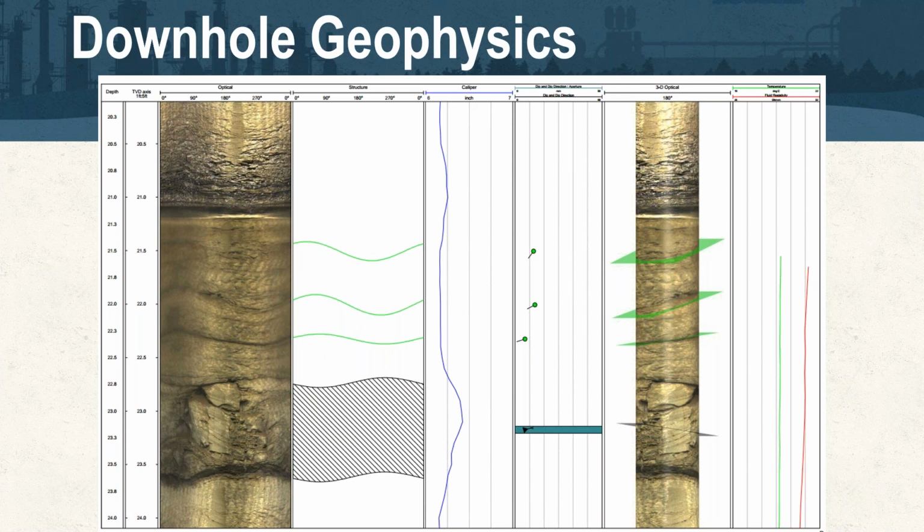In terms of minimizing the number of boreholes installed or that cost, it can be hard sometimes. The tools we showed you on the earlier slide, the West Bay, the Waterloo, the flute liners, the Solent systems, those can sometimes help with that. If those can be retracted from the borehole, that borehole can be used for injection, and those can be reinstalled. So that gives you a borehole that wouldn't need a sister borehole adjacent to it for monitoring. They can be continuously reused.